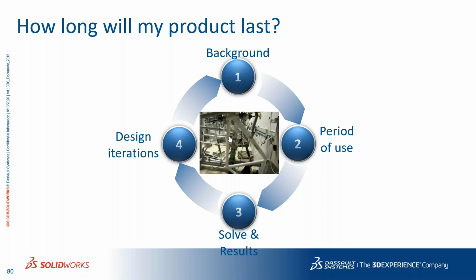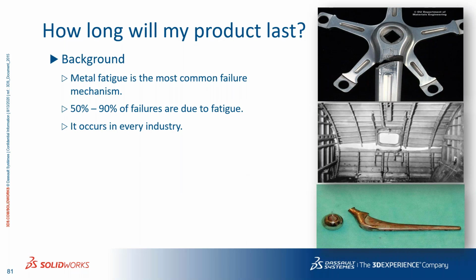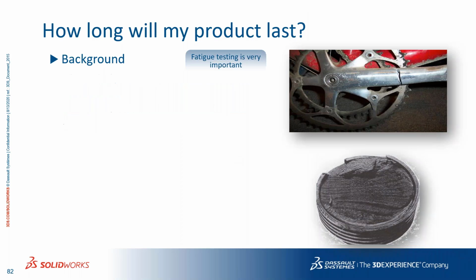You have to keep applying the load, and it might lead to failure after some time. So fatigue analysis is very much required for each and every component. Every manufacturer has to perform this analysis. One more thing I want to tell you: this fatigue analysis is available in the standard package itself. It is one of the high-end analyses, so usually you will not find it at the starting level of analysis, which is linear static analysis. It's a great inclusion in SolidWorks Simulation Standard itself.